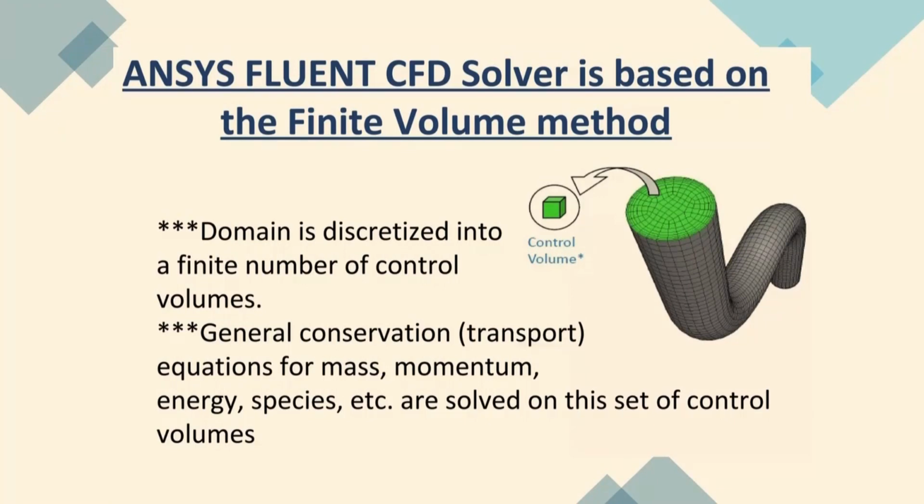The Ansys Fluent CFD solver is based on the finite volume method, as I already mentioned. In the finite volume method, you know that the domain is discretized into a finite number of control volumes. So the conservation equations of mass, momentum, and energy if you have a heat transfer related problem, and species if you have some diffusion problem, these kinds of things are solved based on these control volumes.